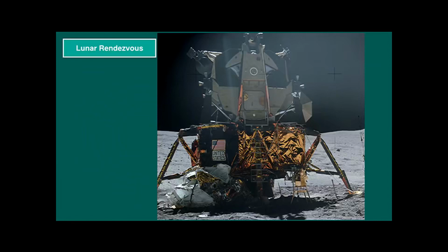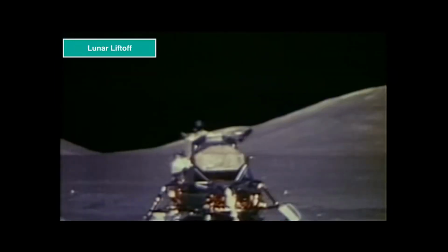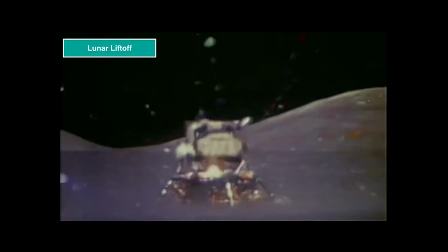Preparation had to start 2 hours before liftoff. We have to align the IMU, and we visually monitor the orbit of the CSM and calculate the rendezvous data. The Apollo guidance computer has program 22, CSM tracking, for this purpose. At liftoff minus 1 hour, we start program 12, powered ascent, and feed it with the necessary data, liftoff time and velocity targets. The Apollo guidance computer performs the countdown, asks for confirmation, we proceed, and we have liftoff.